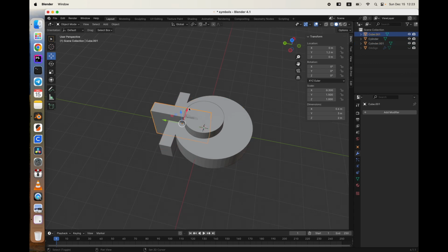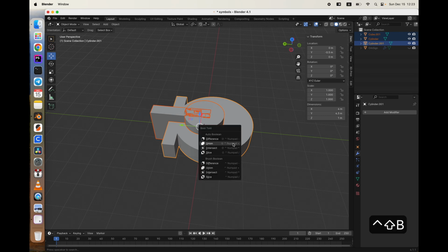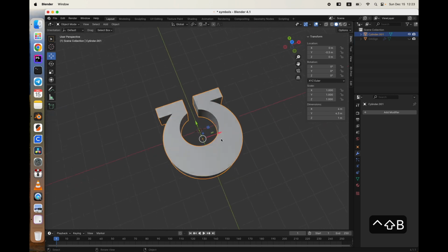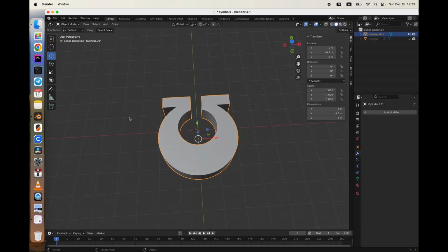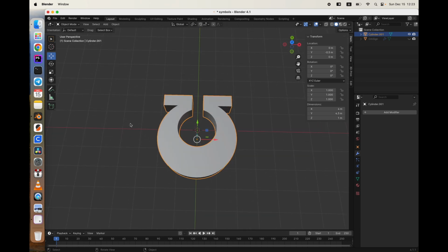And I'm clicking this, and this one last. And I will cut these two objects from this one, Ctrl-Shift-B, and difference. This is called destructive modeling because I'm actually changing the geometry here. We could go with undestructive modeling, but in this case we don't need it.